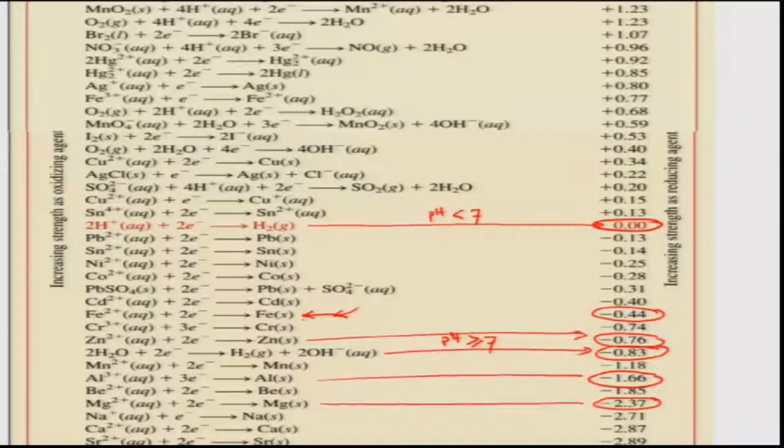So, iron dissolution will be minimized, but of course, zinc dissolution would increase, as well as if we club iron and magnesium, magnesium dissolution would increase. That is why magnesium and zinc are used as sacrificial anodes for protecting iron objects.